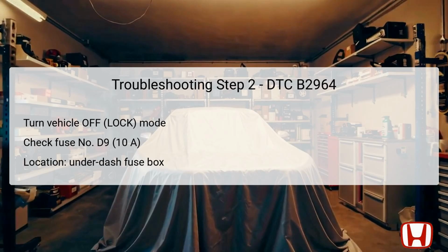If the fuse is operational, this will indicate that the electrical supply to the climate control unit is active. Conversely, if the fuse is blown, it must be replaced. And you should also check for any shorts in the circuit that may have caused the fuse to blow. This step is vital before progressing with further diagnostics.